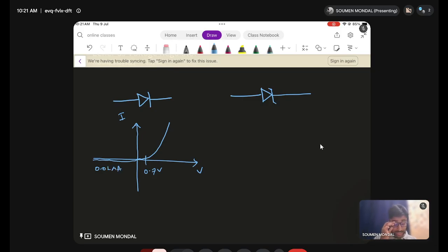And the ordinary rectifier diode is designed in such a way that in reverse bias at very high voltage it eventually breaks down and destroys the diode, whereas in case of Zener diode, we discussed that in forward bias a Zener diode behaves exactly like a rectifier diode, and if it is made out of silicon, the knee voltage will be around 0.7 volt. In reverse bias, at relatively low voltage they can break down.